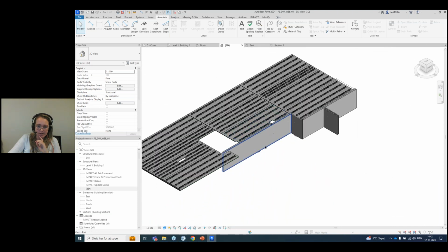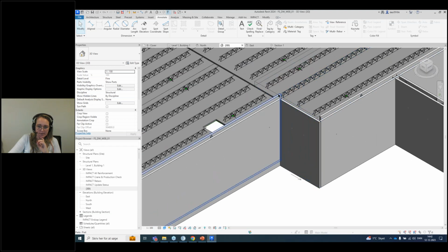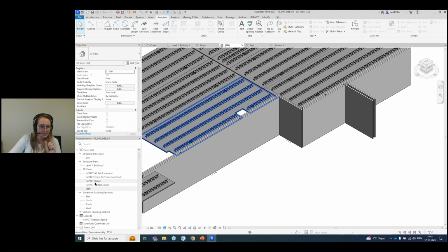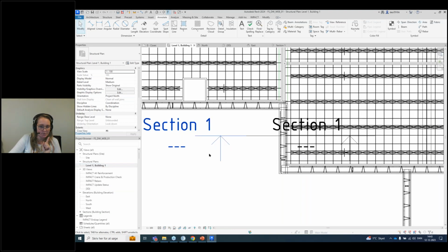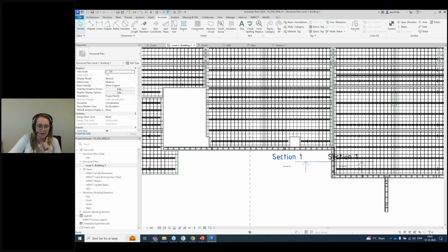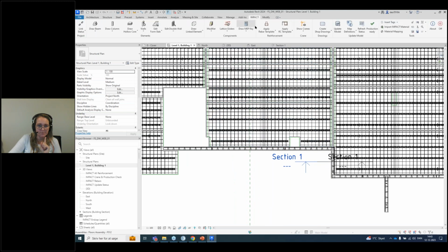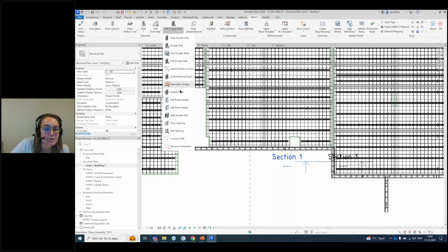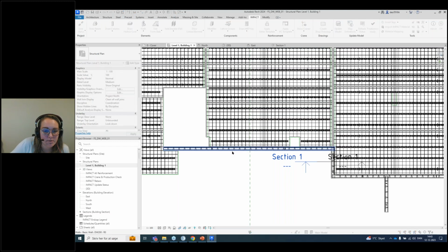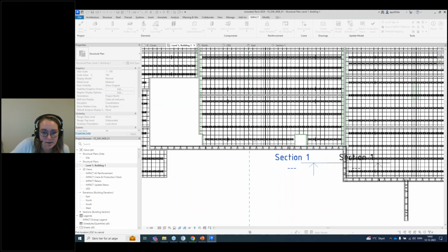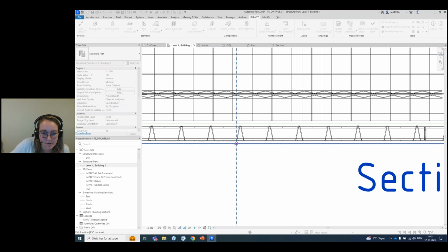But this wall is quite big, I can see, right? So let's split it first, and then we're going to edit panel 2. How do we do the splitting? We have a command for that. Let's do it fast. We go to the floor plan, and we say split double wall, right? We activate the command, select the wall, and then we pick a location. Yeah, I think let's pick this one in here.